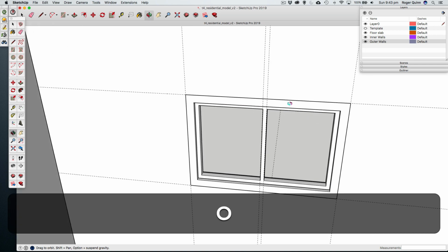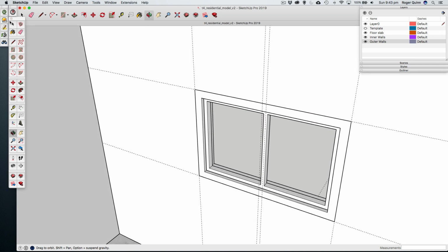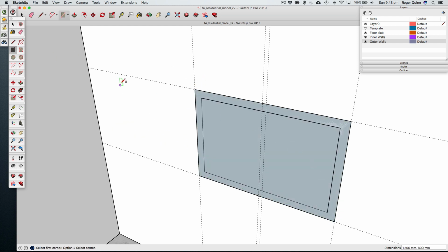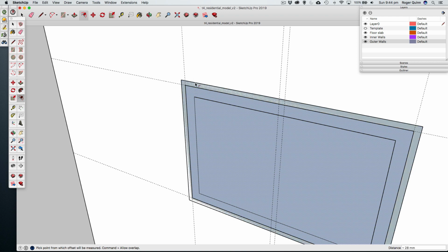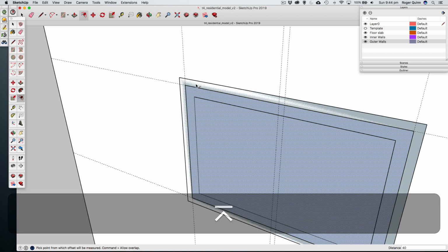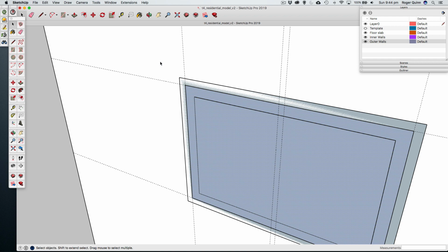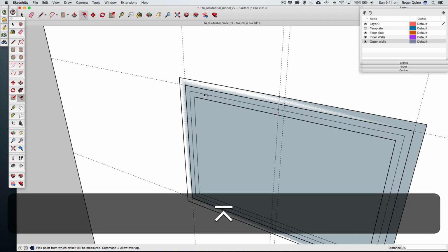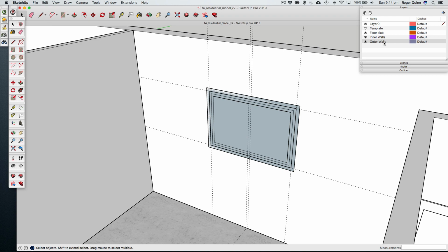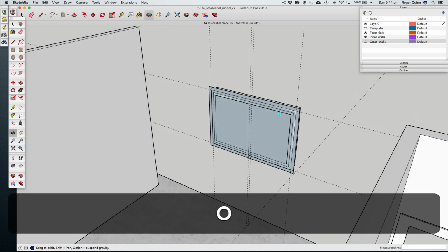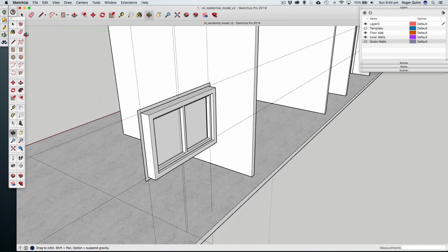And now the final bit, we'll be adding just an internal architrave around the window. So again, I've just drawn a new rectangle that's not part of any group there, it's just sitting on the outside of everything. I want this to be about 70, so I'm offsetting first of all from the original window shape by 40, and then I'm going to offset by 30 on the inside of that line. And this might seem complex at first, but you'll see where this is going in a minute. So I've offset by 40 on the outside, then 30 on the inside, which gives me a total of 70.